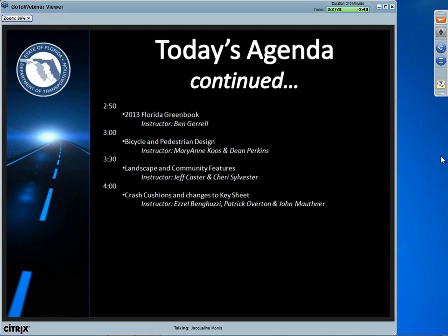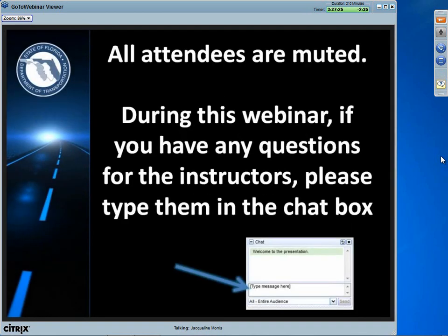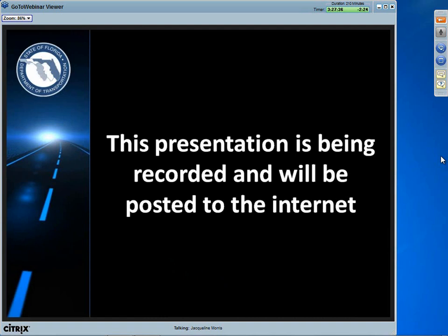Then we had a question. Ben and I were just talking about this one. What is the maximum grade of a side street with a stop sign control along a roadway corridor where a proposed sidewalk will have a crosswalk and would have a cross slope above 2%? I'm thinking that if it was new construction, of course, you would want to have your profile so that your crosswalk would have that 2% cross slope in it. But, right, Ben? Yes. Arterial profile whiz.